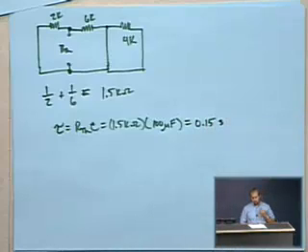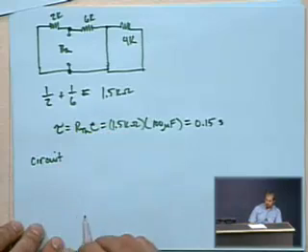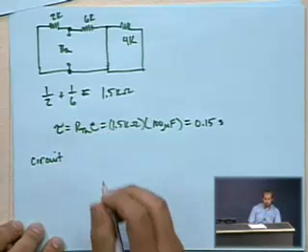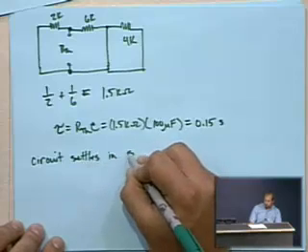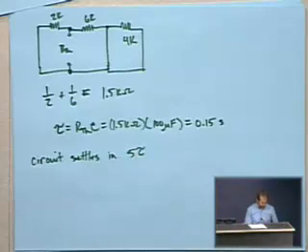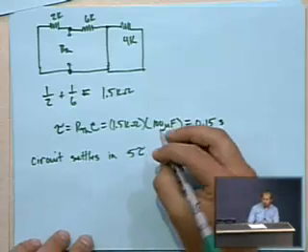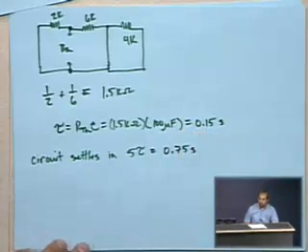It's kind of interesting. As a side note, all of these circuits that exhibit this first order behavior settle down in 5 tau seconds. So that's 0.75 seconds. It takes 3/4 of a second for this circuit.